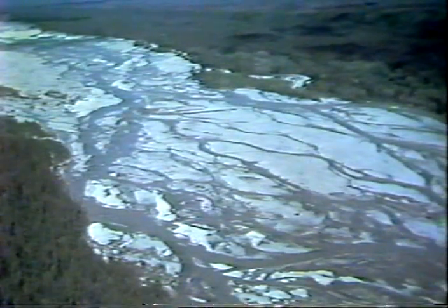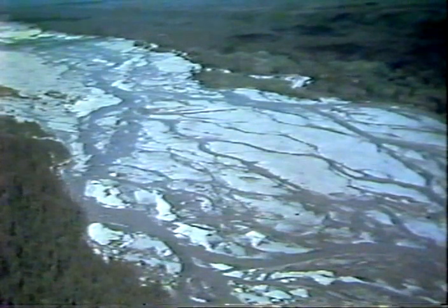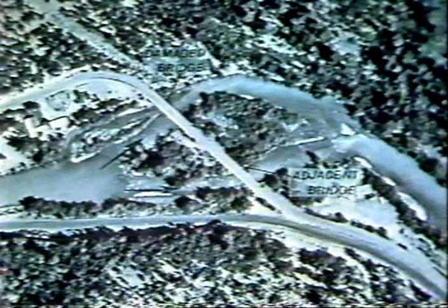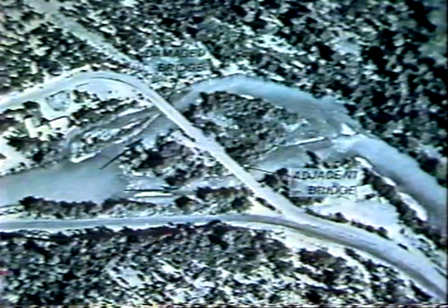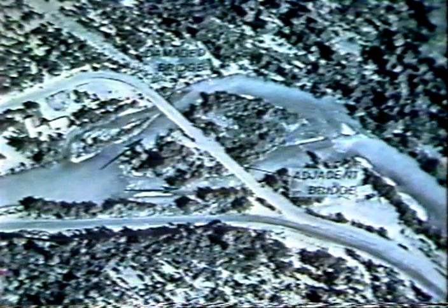They can be successfully confined at a crossing by suitable countermeasures, and a bridge much shorter than stream width can be used. At the bridge site shown in this aerial photograph, the Klickitat River in Washington is anabranched. Of the two bridges, one was damaged during a flood because it received an unexpected portion of the divided flow.